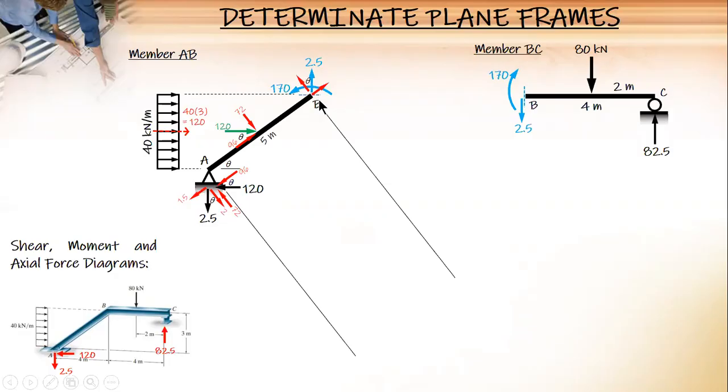Another theta here. So this one is cosine, and we have 2 and then 1.5. So, simplify. Okay. The 72 is not concentrated; originally it is a uniform load. So, we have to convert 72 to a uniform load. Since this is the resultant, we divide it by 5 to get the magnitude of the uniform load. 72 divided by 5 is 14.4.